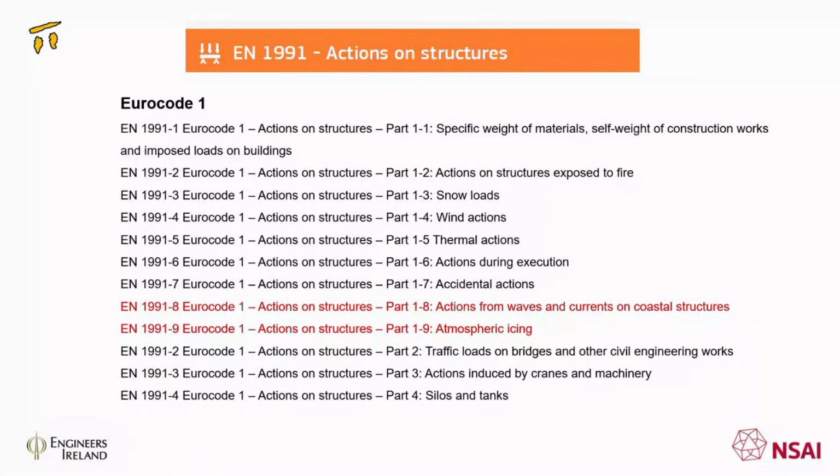And the nationally determined parameters are points which member states can bring in and put their own value in, and there will be a number of these, and they're significant enough in parts of the codes. These have to be determined nationally, and then a national annex is produced which incorporates all the nationally determined parameters for any particular Eurocode, and that is to be produced.